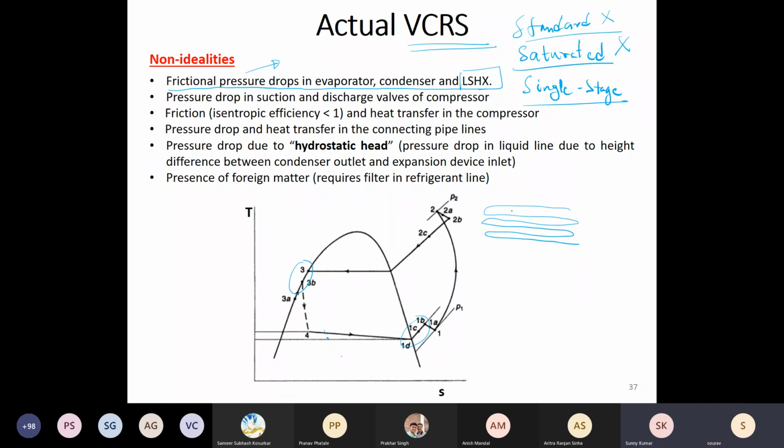And if you actually straighten them out, they'll run into a few tens of meters. They are closely packed in a very compact fashion. But if you straighten them out, they'll be running into a few tens of meters. So your refrigerant is actually flowing through those long tubes, both in the indoor unit and the outdoor unit. So you will definitely have significant pressure drops in the refrigerant line.